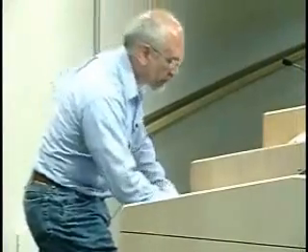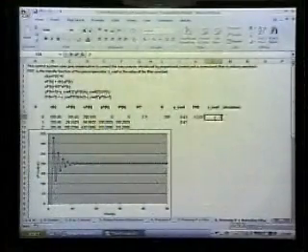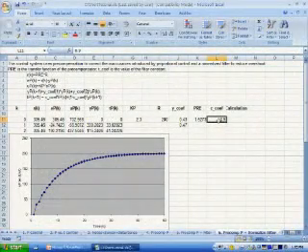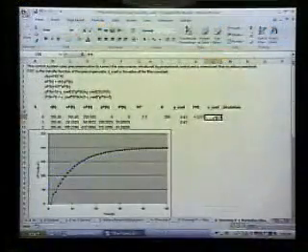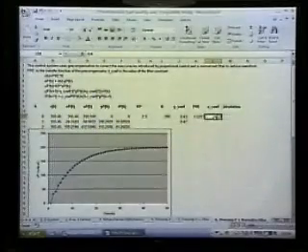So 0 means no filter, and that also means that we have a pole at 0, which doesn't cause us any problem. And then as we get a pole, let's make it more dramatic, a pole at 0.9, let's say, and now we've got a long time to settle. It's almost exactly analogous to adding a capacitor on the signal. Yeah, exactly. Very similar to that. The larger the cap, the smoother the signal, but the slower. But the slower it is, right.